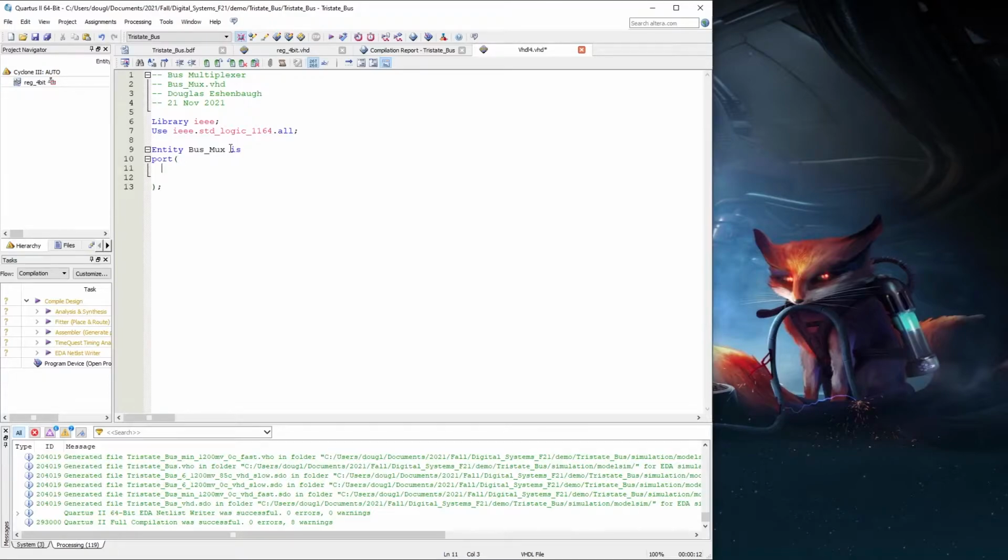So this is a little bit different. For this one, what we're doing is bringing in the two different registers, and then we're going to output it onto a single output, which is the mux by definition. The other thing we're going to do is use a 2-bit select.